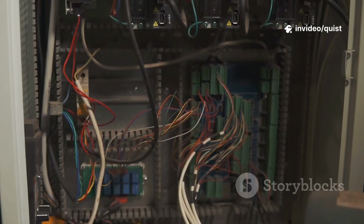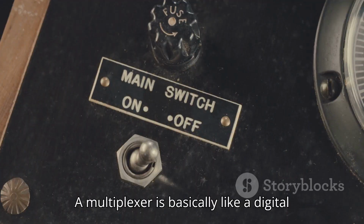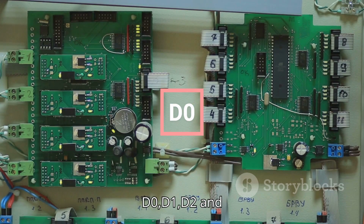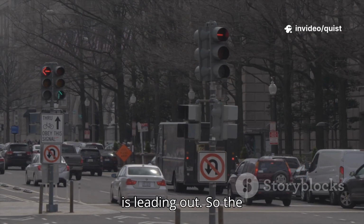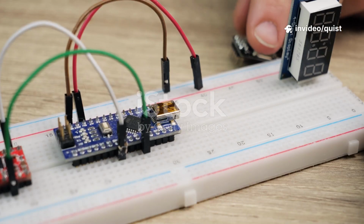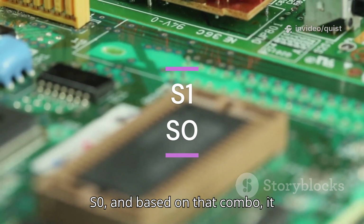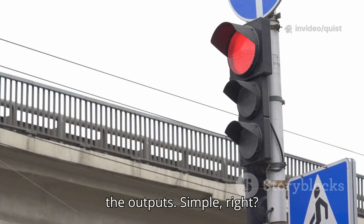So let's get started. What's a multiplexer? A multiplexer is basically like a digital switch. Think of it like a smart traffic controller for binary data. Let's say you've got four data inputs, D0, D1, D2 and D3, but only one road leading out. So the multiplexer decides which of the four inputs gets to take that road. That's where the select lines come in. You provide the multiplexer with two control signals, S1 and S0, and based on that combo, it chooses which input to pass through to the output. Simple, right?